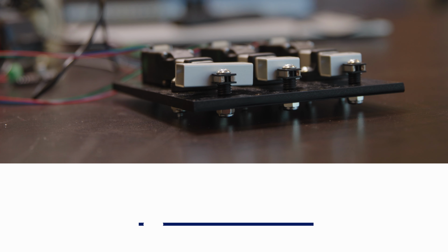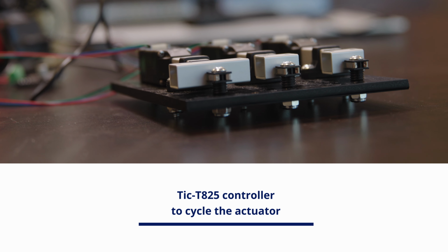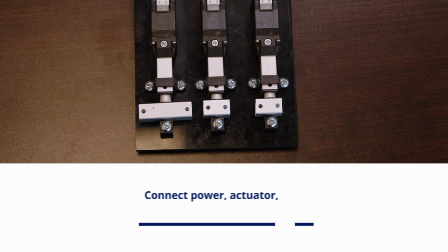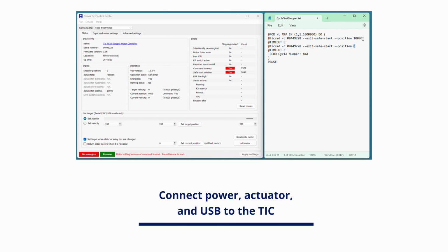For our brushless models, the S20 and the P8 ST models, use the Tic T825 controller to cycle the actuators. Connect power, the actuator, and USB to the Tic. Configure the Tic on the computer using the Tic software and verify it is performing as desired.